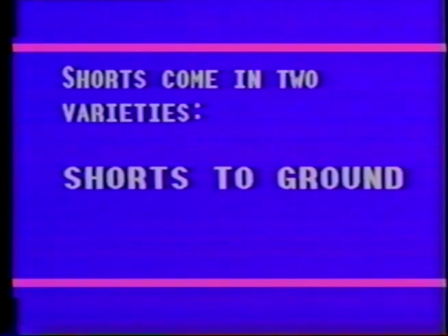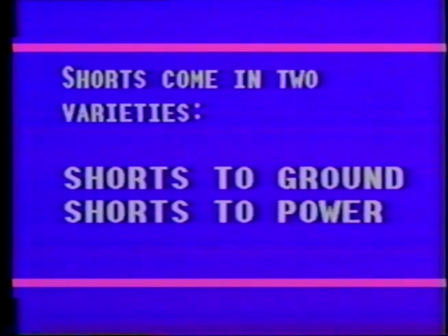Shorts are diagnosed using different techniques. Shorts come in two different varieties: shorts to ground, in which a load or circuit control device is bypassed, and shorts to power, where some other power source is feeding a circuit.